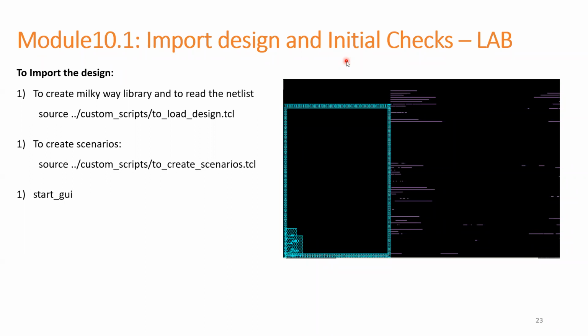The top level engineer who does the partitioning will decide the block shape, and he will give the input and output port locations as well. It can be in DEF format also, so you can just directly take the port DEF and do read def, and these IOs will come and sit on this die, wherever the IO locations are given in the DEF.